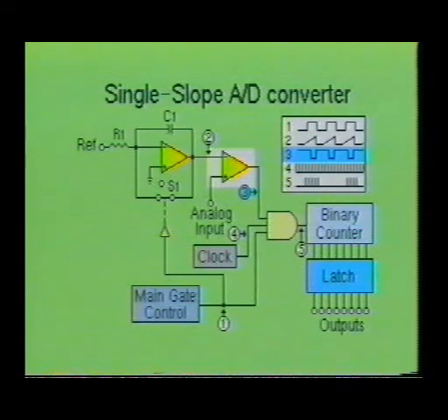The second section is the comparator. The comparator is merely an operational amplifier with no external feedback loop. If you recall, when an op-amp is used with no feedback from the output to one of its inputs, the device will essentially operate with its open loop gain. This causes the op-amp to switch from cutoff to saturation, or from saturation to cutoff, in a very short period of time. Basically, the op-amp works as a switch and is not linear.